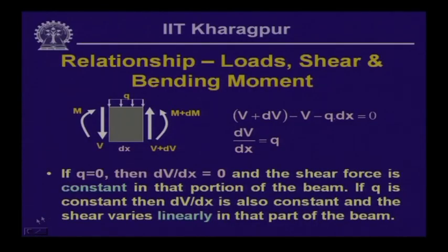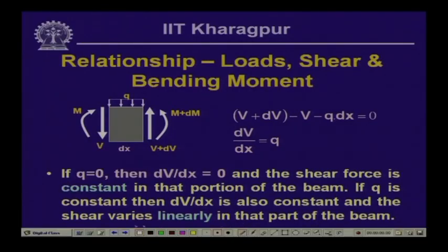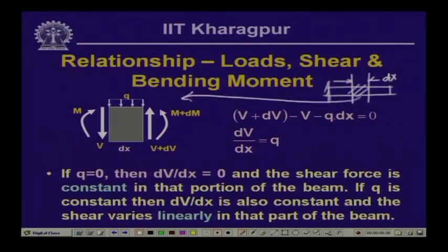Now, to do that, let us look into some of the aspects of that, how different kinds of loads can be related with the stress resultant quantities, which are nothing but the shear force and the bending moment. Now, if we consider a small segment of the beam, let us say that we have a beam over here, which is supported at this particular end, and we like to take a small segment out of it, which is of length dx. So, this particular segment is drawn over here.